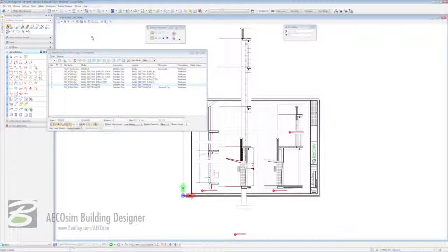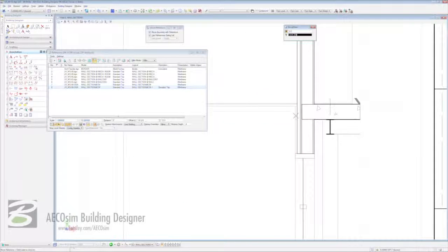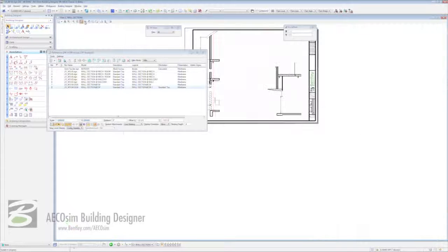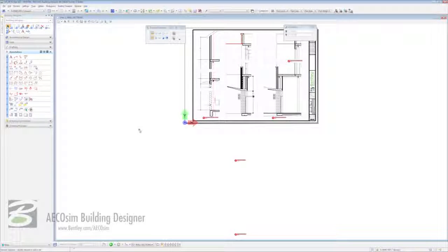Sort of. Not quite. Because what I need to do now is actually move my other reference down, and there is method to this madness. I'm going to draw it down here, lock it in, so it's locked in there. And what I'm going to do over here is zoom in to this point, and then right click. And I'm going to come back out and use again my reference clipping, select the icon, and select the bounding box around it. And there I have those two sections aligned and placed to scale, so very efficiently.